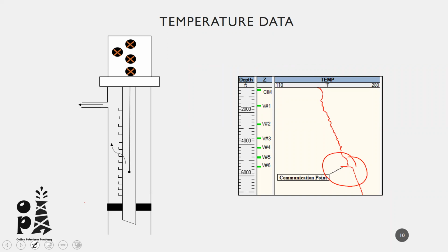This anomaly means there was flow through this valve from tubing to the annulus side, which means that the check valve in this valve was failed, and this valve must be changed to solve the communication problem. After performing this job, slickline changed this valve and repeated the communication test, and there is no communication now, and the problem is solved.